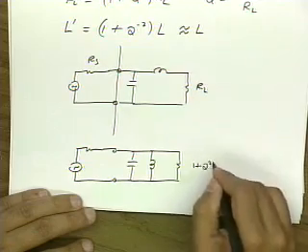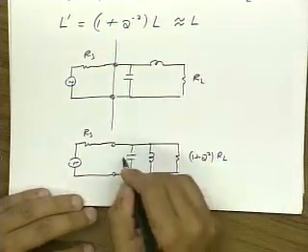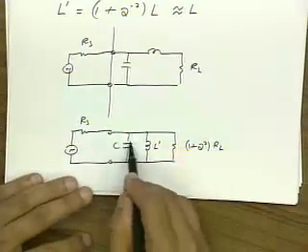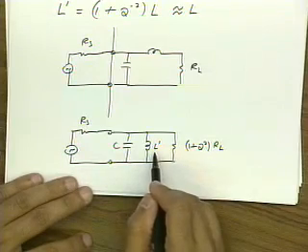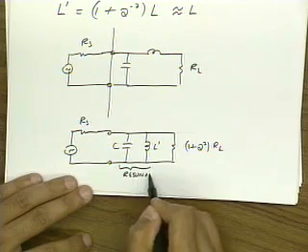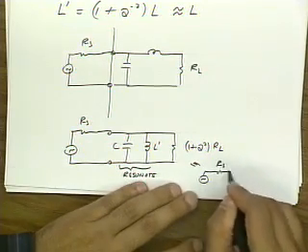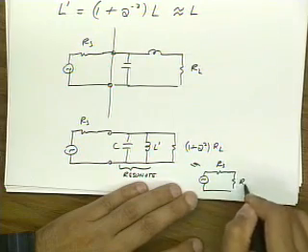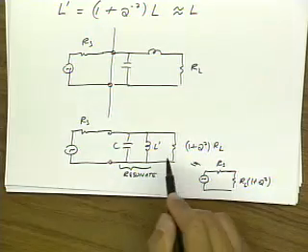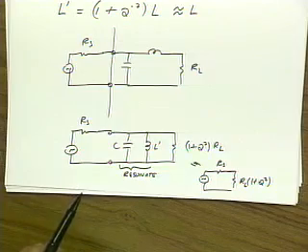This is 1 plus Q squared RL, this is RS, this is C, this is L prime, and therefore I will pick C to resonate with L, and so then the equivalent circuit breaks down into this simple form. It's just a voltage divider, right? That clear? Any questions?